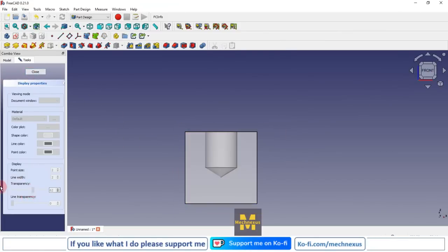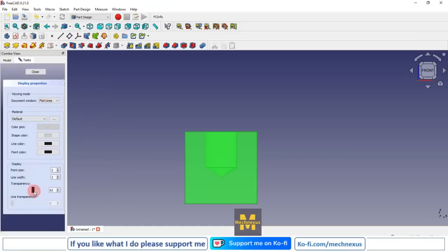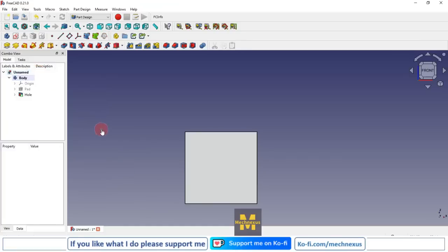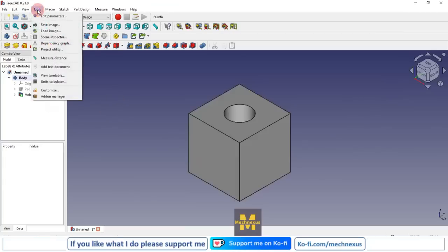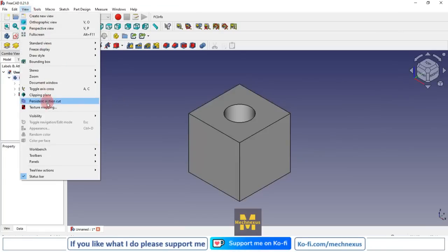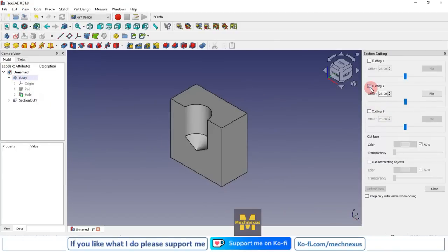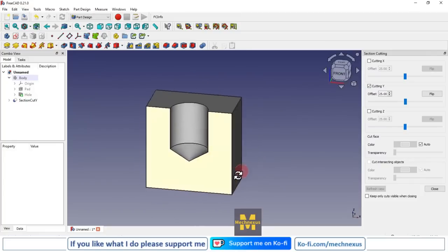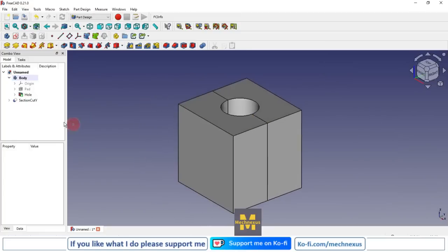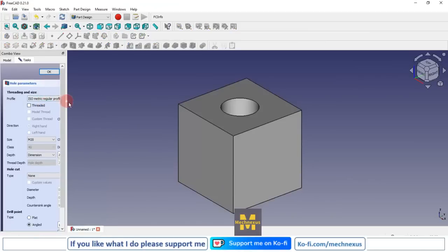Now I will keep my transparency at the default. Go to the appearance again. Now we will switch to the isometric view and we will take the sections. For this, switch to the View tab and click on the persistent section cut and select here the Y-axis and say OK. So you can see how we have created the M20 threaded hole. Now we will edit the hole feature and try some other holes.